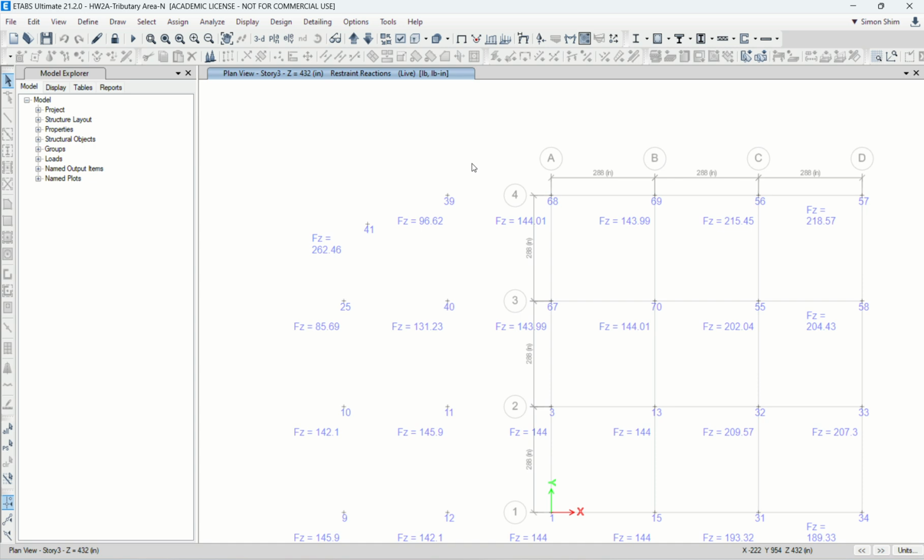Most likely a high-rise building is very complex. A column is not always straight down. It slightly moves in and out. Not all columns are on the grid. Residential building, I will show you later. It's not going to be on grid, because of the program. For commercial buildings, in many cases it's a simple box or rectangular shape, and the columns go straight down.